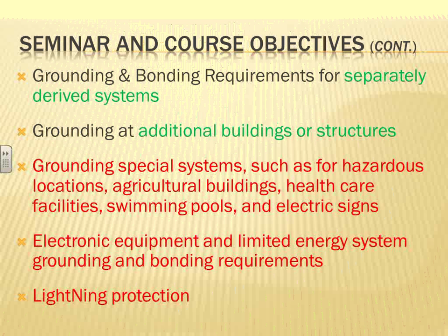There is a whole different grounding and bonding, guys, for data centers. If you see a data center, all these racks, you bond them, and you'll see 4/0 tying all these racks together, the backbone of the grounding system. That's completely different from what the code requires. That's strictly for the protection of the electronic equipment, above and beyond what the NEC code book requires when it comes to grounding and bonding.